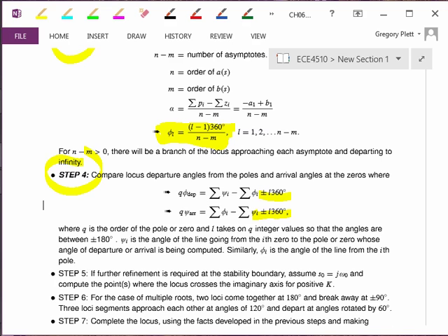And when you have a root locus plot and you have a desired point s0 through which the locus passes, you should be able to find the value of K that puts the poles at that point. So that concludes our chapter on root locus analysis. From here, we're going to go into a chapter that leverages all of this information and is thinking about root locus design. How can I design a controller to meet the transient response specifications we talked about earlier using ideas that we garnered from the root locus plots?